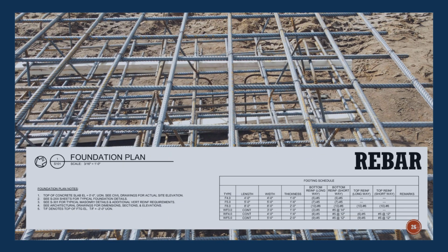Let's look at the F8 footings. You will see columns in the schedule for both the top reinforcing and the bottom reinforcing. Notice how only a couple of footings get a top mat. We also have a column for long ways and short ways. Short ways being the smaller dimension of the footing. The F8 footings are square, so both ways are even.